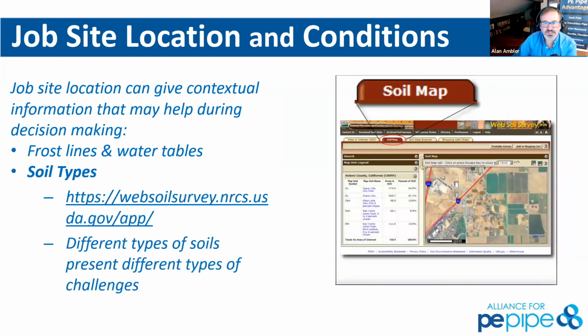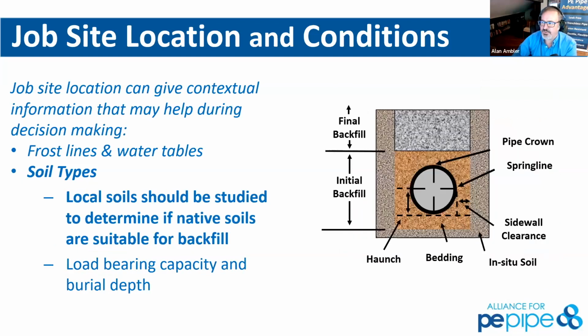There are some handy things available for you for references. USGS has good soil conditions for you. That's typically the top portion of the soil column, and not something that's suitable for exploration for deeper depths as we go through there. Obviously, as competent design engineers, you want to be able to answer the depths of the soils when we get into complex drills or any other complex installation as we go through. But these simply help us understand the project locale. You can find these in the references fairly quickly.